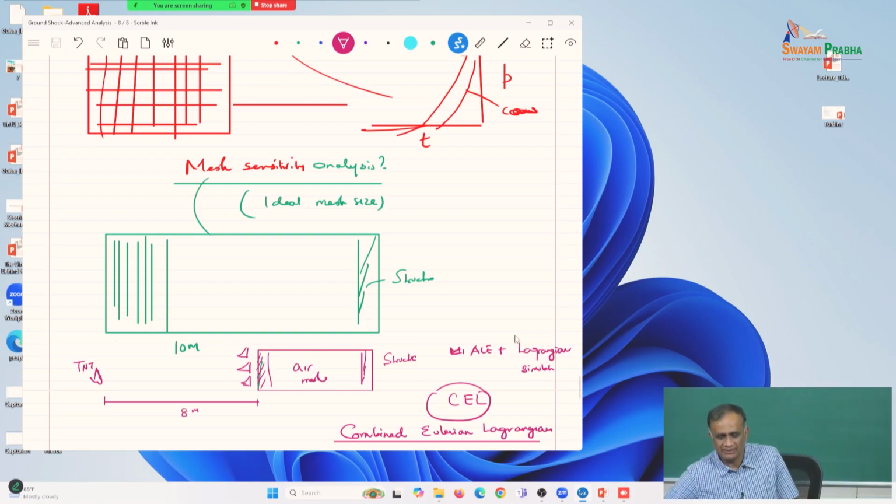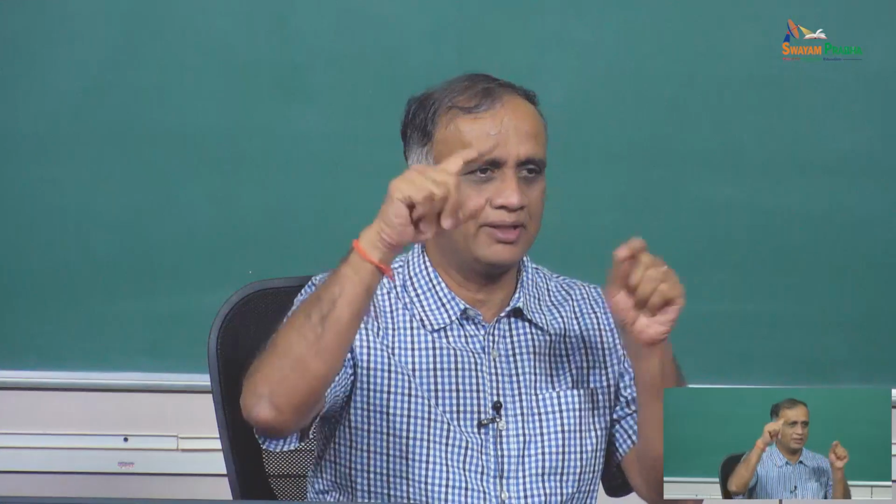So the complexities are, even in simulation itself, right? We talked of the mesh. If you're having a complex structure which has got sharp corners or which has got many variations, then you start getting into the mesh quality. So mesh quality, people invest a lot of money in, there are companies that do nothing but sell meshing software. They charge a lot of money for it, especially for commercial purposes. Research purposes, you might get it a little cheaper. So the quality of mesh is very, very important in certain types of applications.